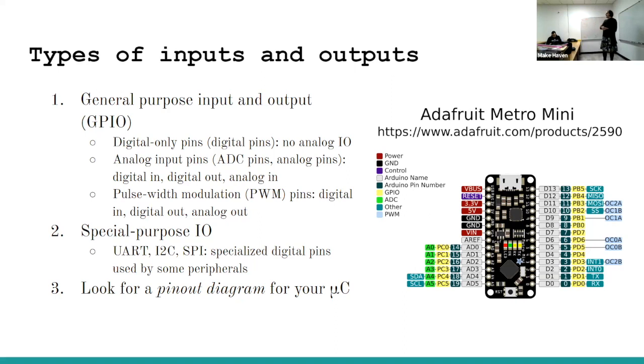That means that when you hook it up to your microcontroller, you have to hook it up to whatever the I2C pins are on your microcontroller. You can't hook it up to any random pin on your microcontroller. Yep. And the way that you're going to find all of these things is that you're going to go on the internet and say, I have a microcontroller called, let's say, Metro Mini, and you're going to search for a pinout diagram. And it's going to come back with a picture like this.